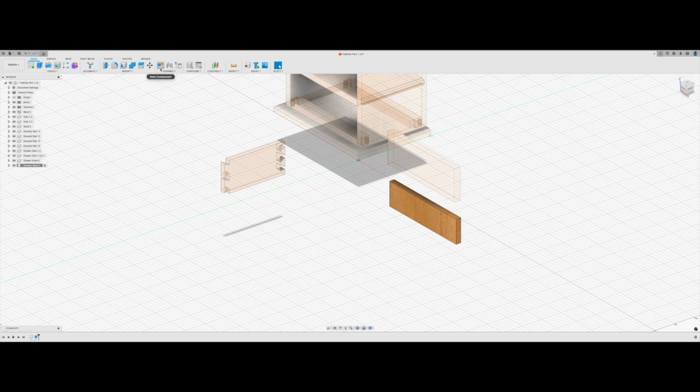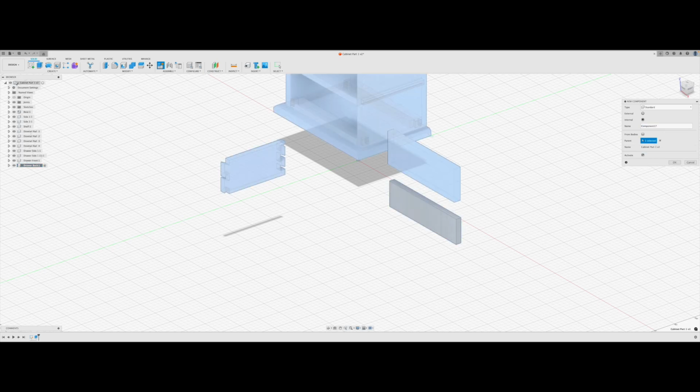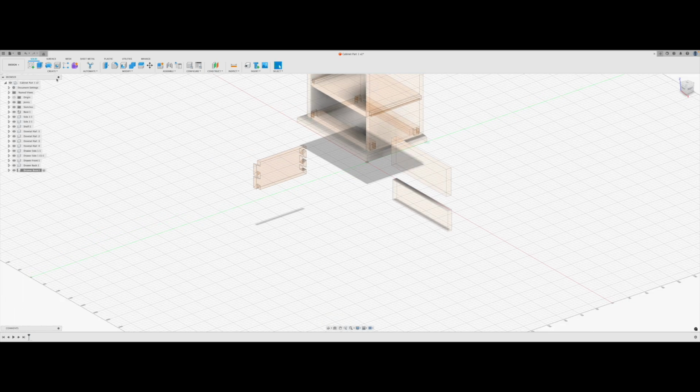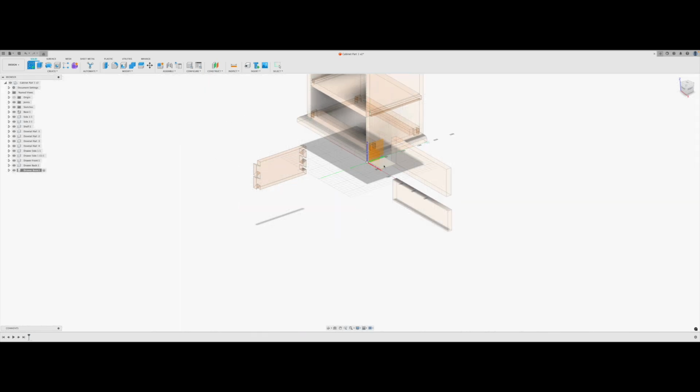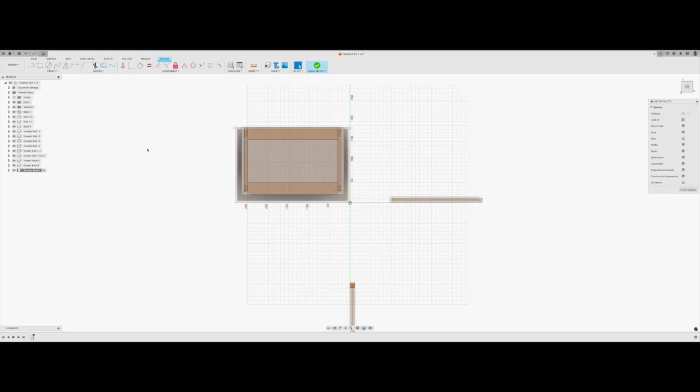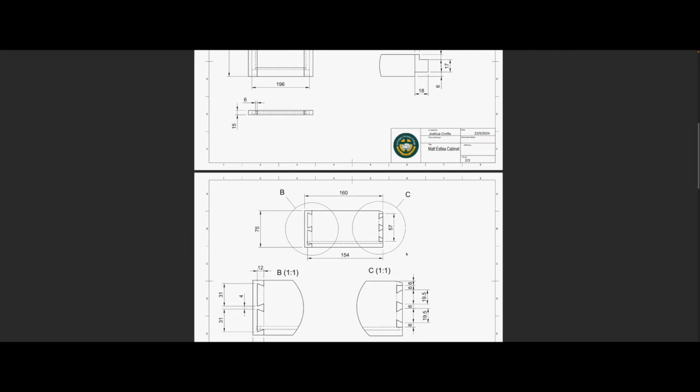So let's maybe draw our base first. So we're going to jump into here. We're going to make sure our parent is this top one. Go draw base, because we can figure out those dimensions off our drawing. We're going to go sketch. We're going to look down at our base. Half a rectangle. There he is there. Then we're going to draw our dimensions.